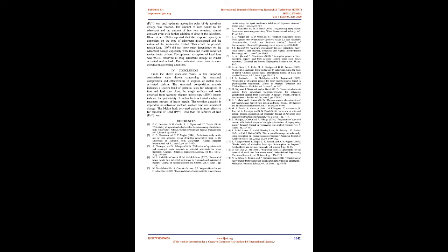The adsorption of iron, Fe2+, in Fig 3, shows that equilibrium was attained at 60 minutes for urea activated melon husk, 80 minutes for NaOH activated melon husk and 70 minutes for H2SO4 activated melon husk, while for the lead, Pb4+, ions adsorption as shown in Fig 4, equilibrium was attained within the first 10 minutes for NaOH and H2SO4 activated melon husk and 20 minutes for urea activated melon husk. Therefore contact time can be optimized to 70 minutes, i.e. 1 hour, 10 minutes.